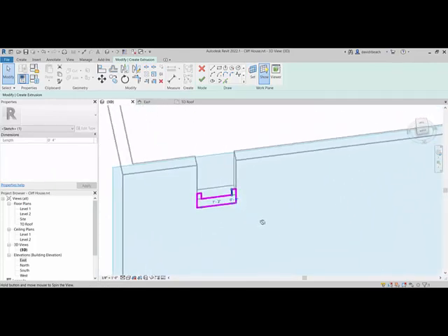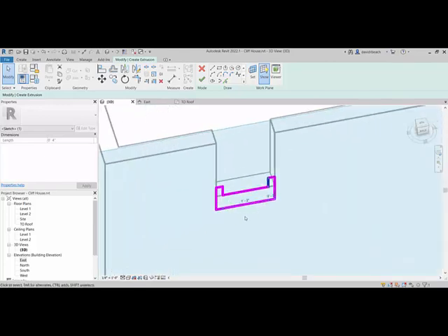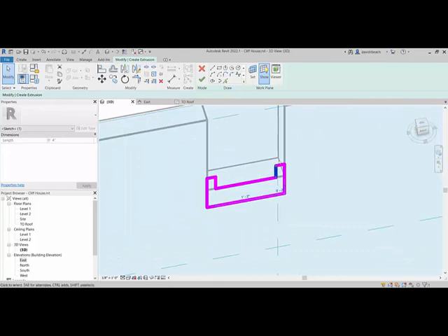Who can tell me what other assumption I've made that's terribly wrong? So roof is filling up with water. It's a downpour. Water starts running in this direction. What happens if it hits this little spot right here? It's like one more thing for the water to have to go around, which means it's one more spot for the roof to leak, which means the roof's going to leak. So those really need to happen.